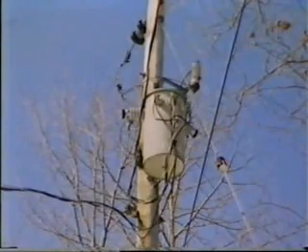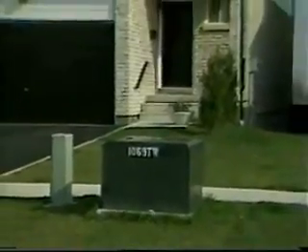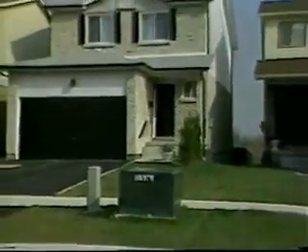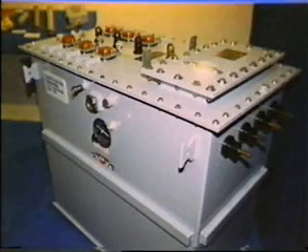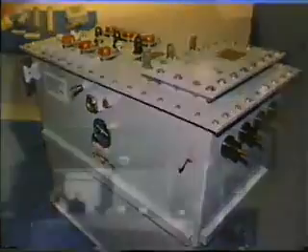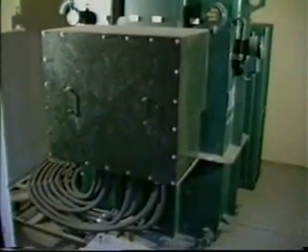For example, we have the pole-type transformer for overhead service, and pad-mounted transformers for underground service. These are actually located above ground. Underground transformers include the submersible type and also transformers which can be buried directly in the earth. And network transformers serve secondary network systems and spot networks, and these are usually located in vaults underground. Within these four basic types, there may be many different variations on the design.